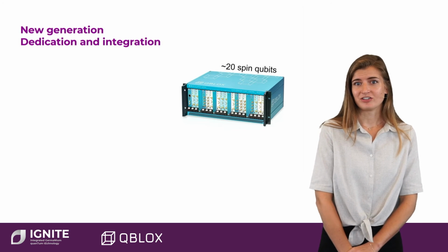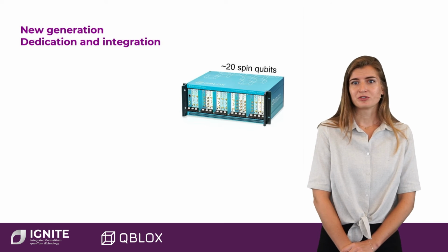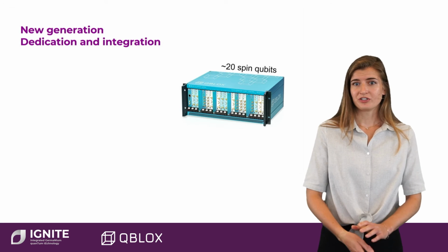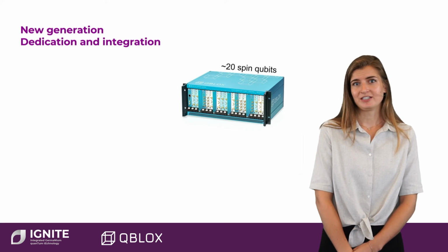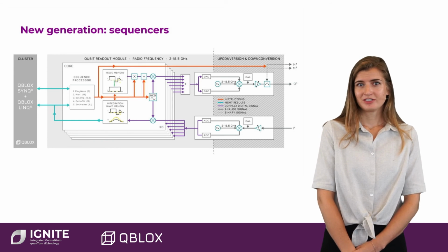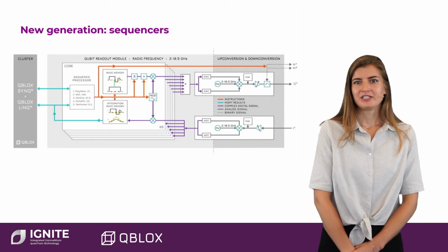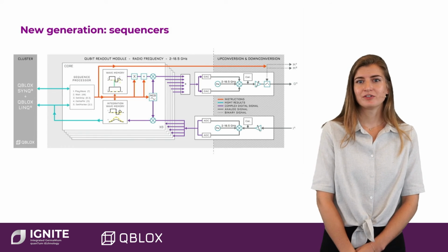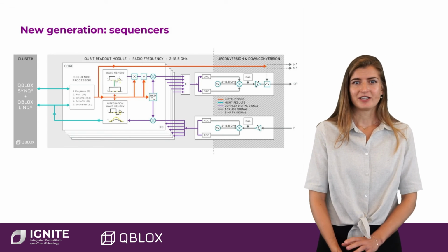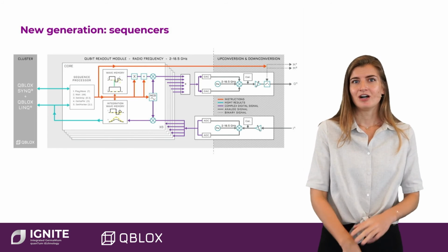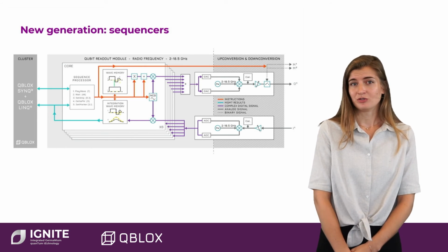Fully integrated architectures offer you all you need for qubit control and readout in a massively scalable fashion, and with modular components to personalize your electronic stack to your experimental needs. Where the arbitrary waveform generator used to be a staple instrument, it is now being replaced by onboard sequence processors that allow for generating waveforms on the fly. Waveform envelopes can be stored in the onboard memory and modulated in real time, giving you the flexibility to vary amplitude, offset, phase, and frequency on the fly without the need to open a connection to the PC to reload your waveform.